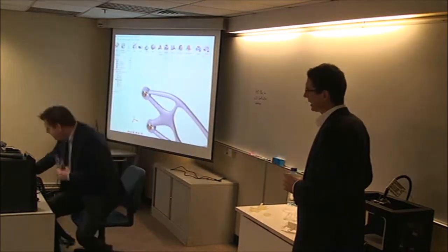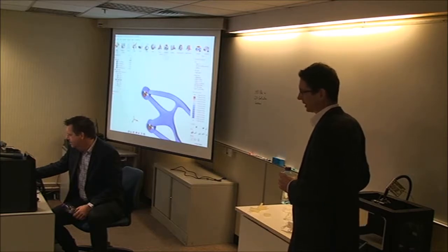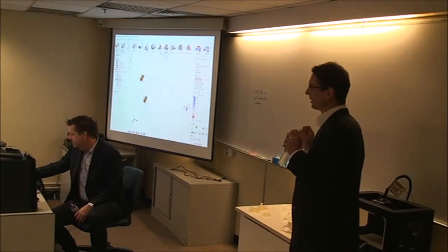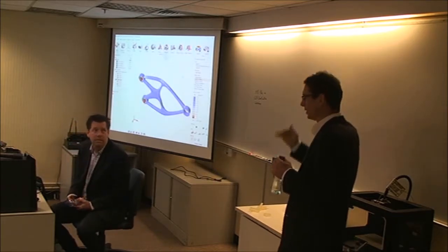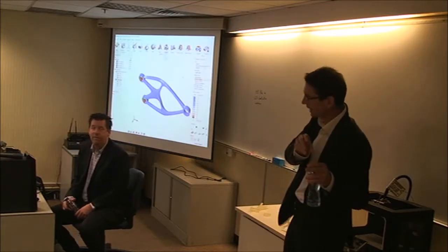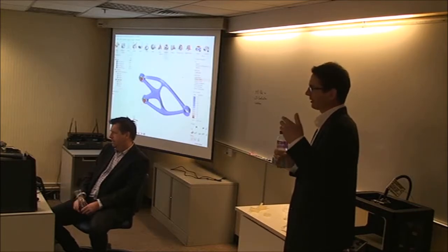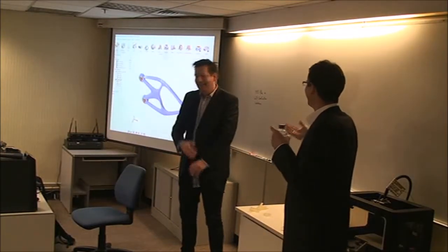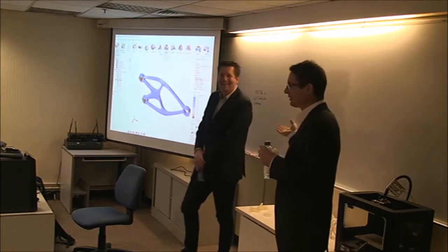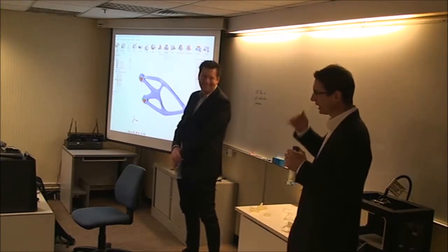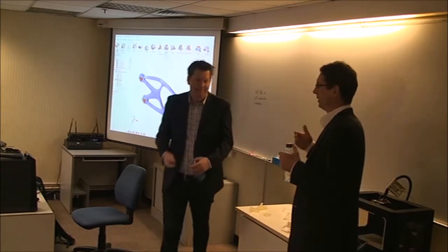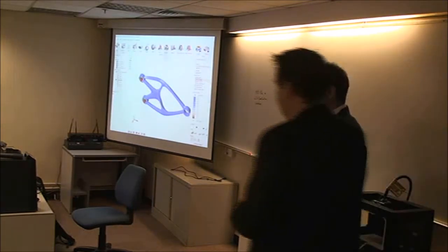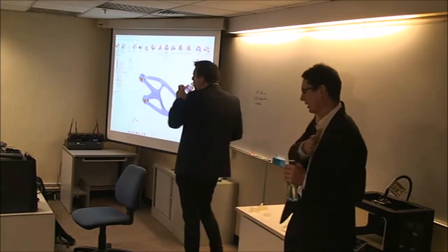So at the beginning, as every engineer, you have to define the allowable stresses, and our software will guarantee that you will not reach or overshoot these allowable stresses based on the load case that you have defined. So finally, what can go wrong is that you see an overload because something happens. Say someone had a good breakfast and is sitting on the bike, and the loads are higher and they reach this stress target, or the material manufacturer is giving you a different material and you assume that's the original material. So there are a lot of things that can go wrong in the whole process.